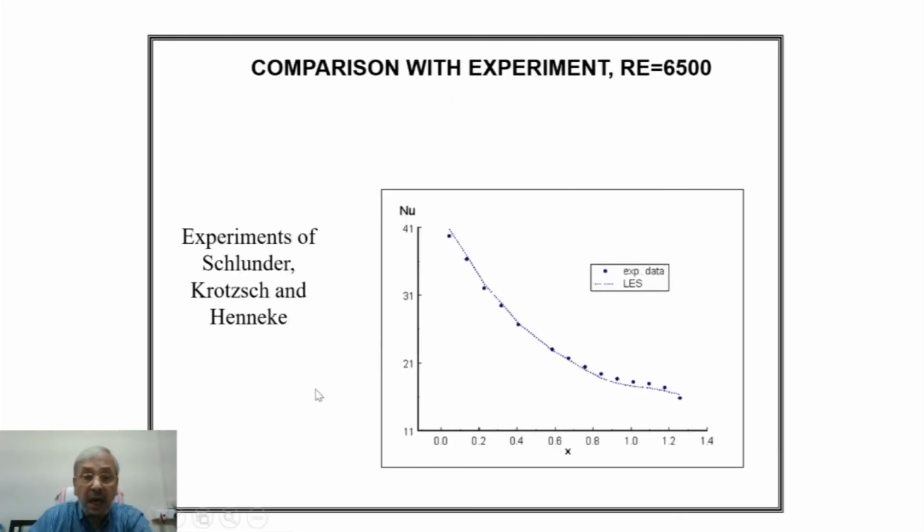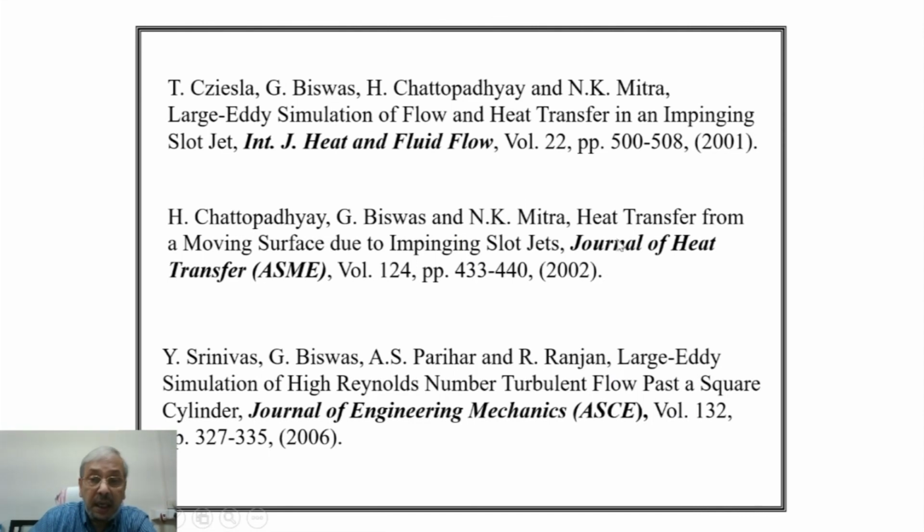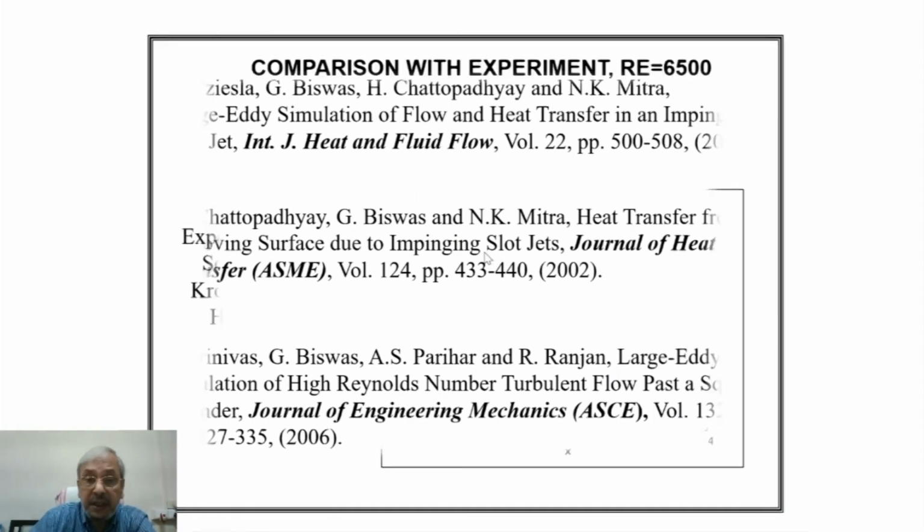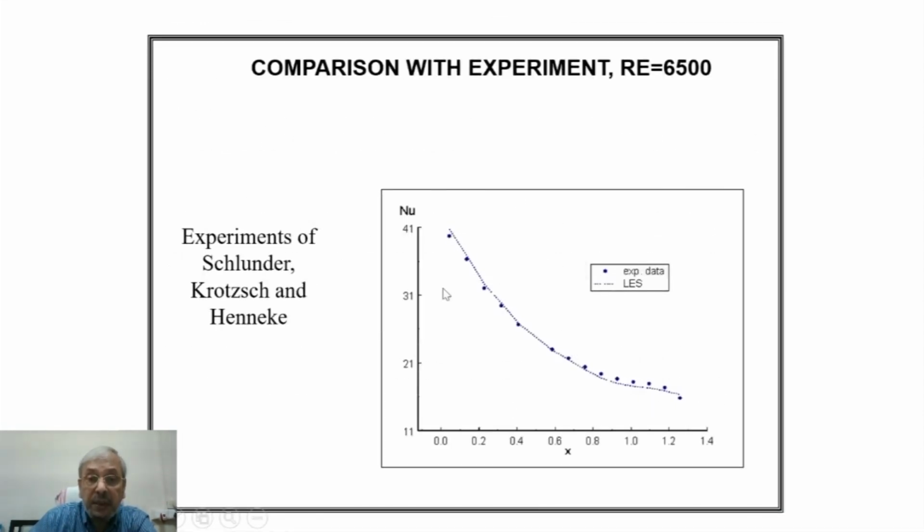Now in the second investigation, we found out this is on a slot jet. Again, slot jet is being used for cooling a heated plate, and these dotted lines are earliest calculation based Nusselt number plot, but Nusselt number, this is span wise average Nusselt number, and one side from the slot jet center line.